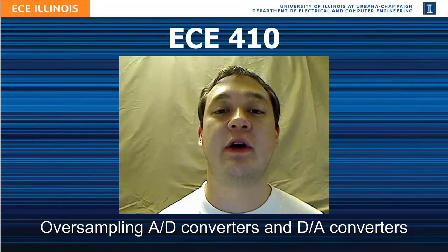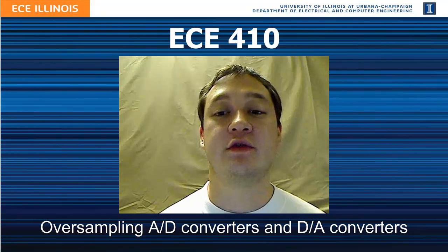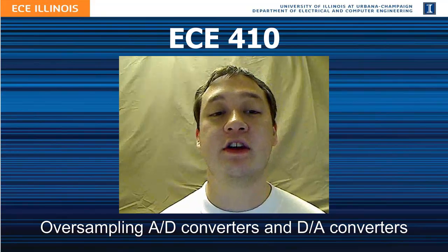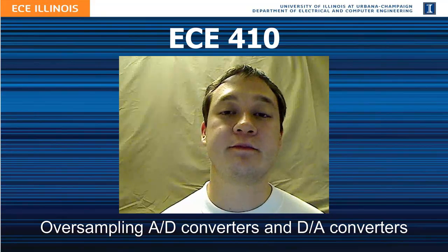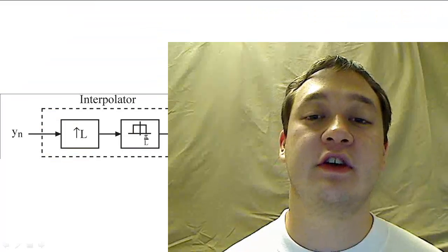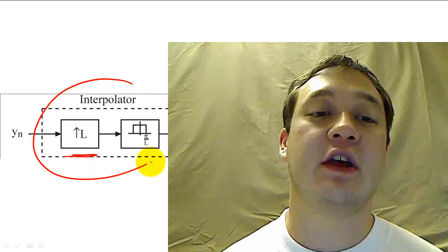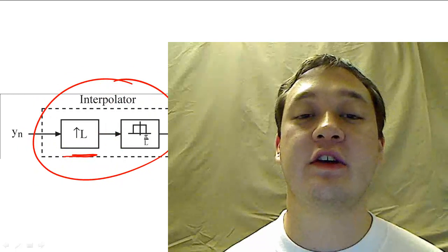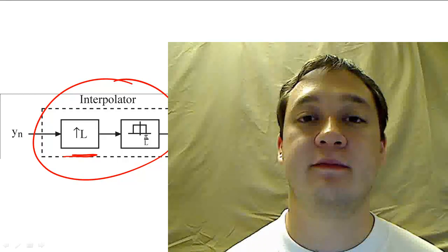If we are dealing with a primarily digital system, such as an MP3 player, oftentimes the signal processing unit will be very sophisticated and powerful. So, we will want to make the analog circuitry as simple as possible to save power. In this case, upsampling and interpolating the output y[n] can allow us to create a simpler analog filter that smooths out our zero-order hold.